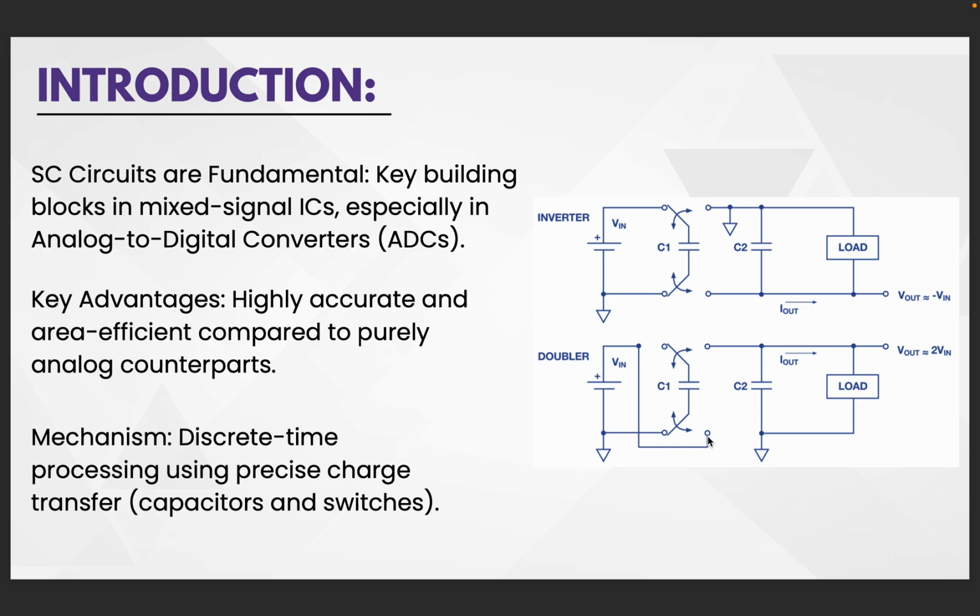Switched capacitor circuits are extremely important in modern mixed signal VLSI systems. These circuits are commonly used in analog to digital converters, filters, modulators, and many communication systems. Rather than relying on precision resistors, switched capacitor circuits use capacitors and clocked switches to process signals in the discrete time domain. This provides very high accuracy since capacitor ratios can be controlled well, excellent area efficiency, better integration with digital CMOS technology, and high immunity to component variations compared to continuous time analog circuits.